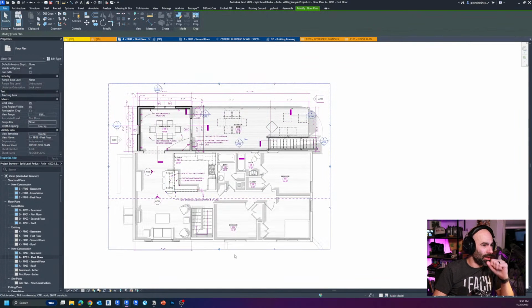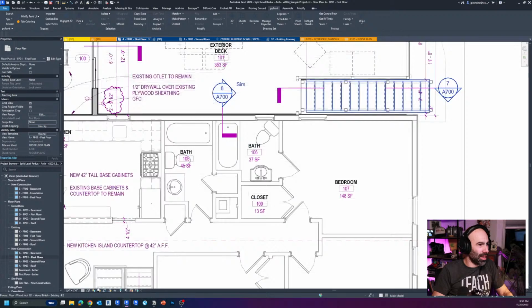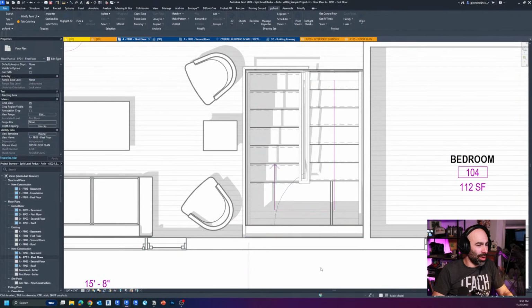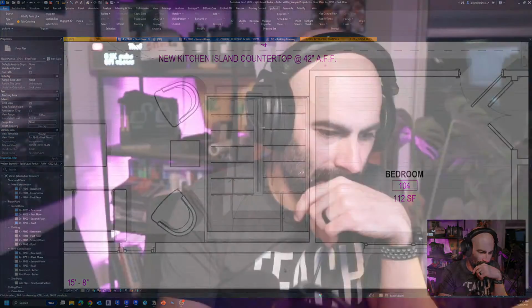All right. So, actually, you could probably see it there, but you'll notice that. See how nice and long this shadow is, and this shadow helps there. And then when I go over here, this shadow's going all the way down to the floor. So none of my floor plan views have a ground plane shadow, so that when you have openings and whatnot, it actually gives you that visual of the openings going down. So just some things to keep in mind as you're going through it.